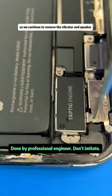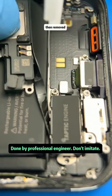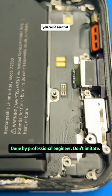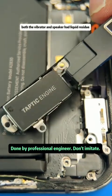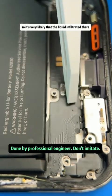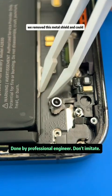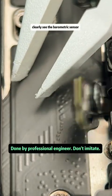So we continued to remove the vibrator and speaker, opened the speaker to disconnect the vibrator's flex cable, then removed the vibrator and speaker. You could see that both the vibrator and speaker had liquid residue, and our so-called barometric sensor is also located below. So it's very likely that the liquid infiltrated there and corroded it. For the restart issue, we removed this metal shield and could clearly see the barometric sensor.